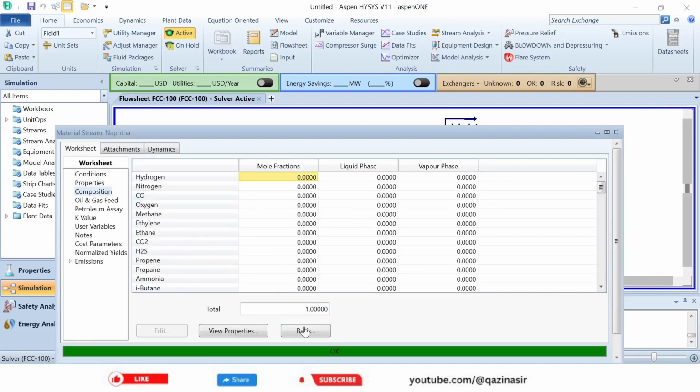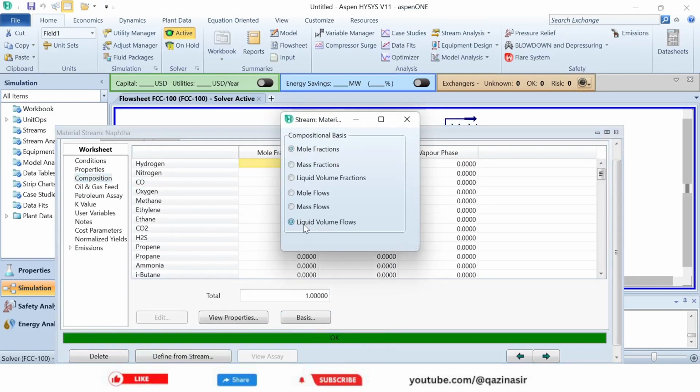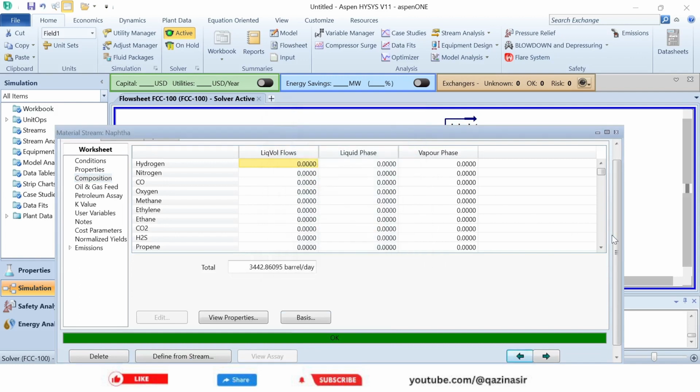However, if you go to naphtha, you can change the basis to liquid volume percentage, and then scroll down, you see we have some fractions in a temperature range between 110 all the way to 300 degrees Celsius. So this is the naphtha information that we have.